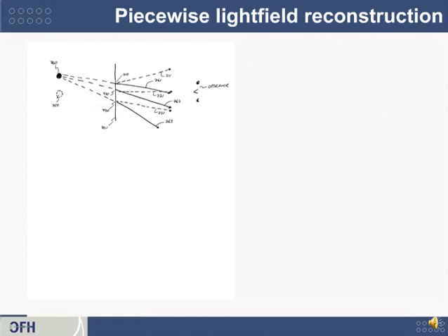Here's an example of how you'd make one dot, one voxel of an image float in space. This is a top-down view. On the left you see the dot you'd like to reconstruct, which is numbered 760. There's the image plane, or the display surface, which is 701, and the observer on the right. As you can see, if there was a real dot floating behind the screen, it would be approximatable by a series of rays which leave that screen, going in a variety of different directions. Likewise, if you wanted to reconstruct the dot 750, which is in a different position, it would generate rays leaving that screen in 3 different directions.